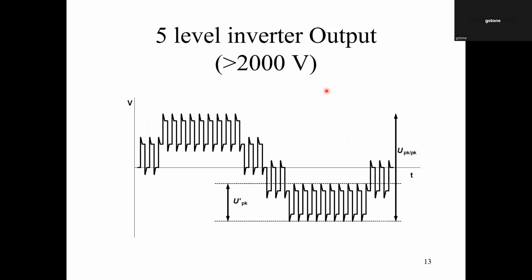But then as we got to higher and higher voltage machines, as I said, we have motors out there at 13.2 kV now, and they tend to stack these inverter stages on top of each other or combine them in some way in a transformer, so that there are even more levels. And I'm aware of inverters that have got up to 11 levels.